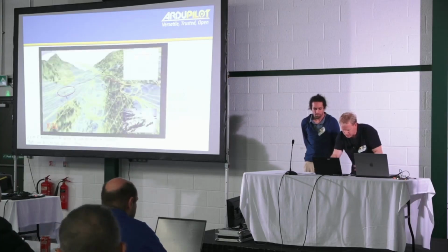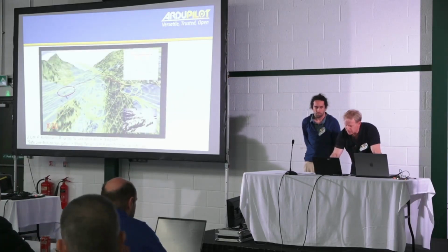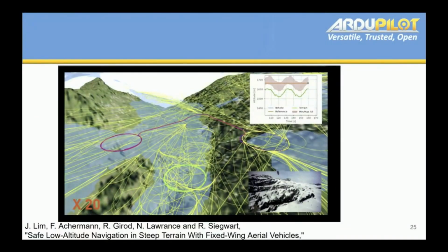So it's very powerful. The underlying paths use a Dubins curve. So it assumes that there's a safe place to start. You can find a loiter to start, and you can find a loiter to end. And then given those two constraints, it will see if it can find a feasible path, honoring various climb rate limitations for the plane, but also making sure that it stays within altitude bounds and satisfies the terrain constraints. The public version doesn't include fences. I believe that there are private repositories which do, but we don't have access. So that was the inspiration for our work.